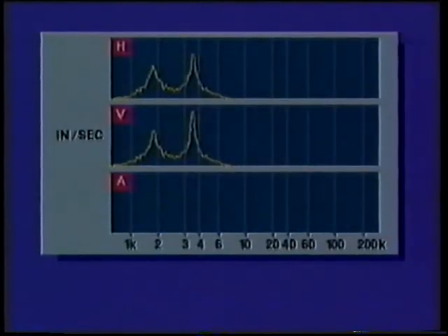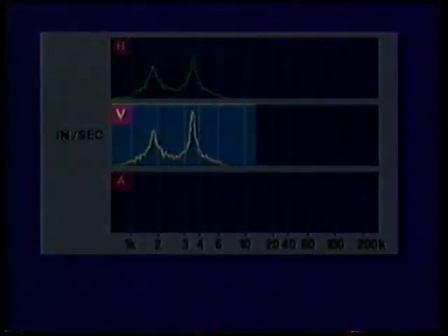As you would expect, the amplitude of the vibration will increase as the amount of looseness increases, and the amplitude at 2 times RPM will usually be greater than at 1 times RPM. This is because as the bearing rotates downward, it moves at a greater velocity through its rest position. This higher velocity is due to the gravitational pull on the heavy spot and the rotational force of the shaft within the bearing. Since mechanical looseness allows any residual unbalance to show up, the vibration caused by this condition will be primarily radial in direction. The peak amplitudes will occur in the radial directions, here vertically.